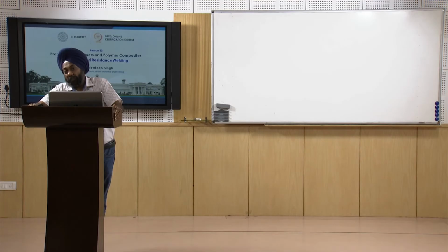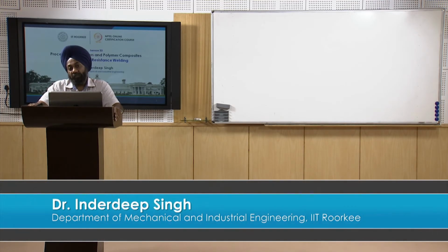Therefore, we have to be careful while selecting a joining technique for polymer based composites. For thermosets, since no heating is required, we can go for adhesive joining or mechanical fastening, but specifically for thermoplastics we can choose resistance welding, induction welding or microwave joining.